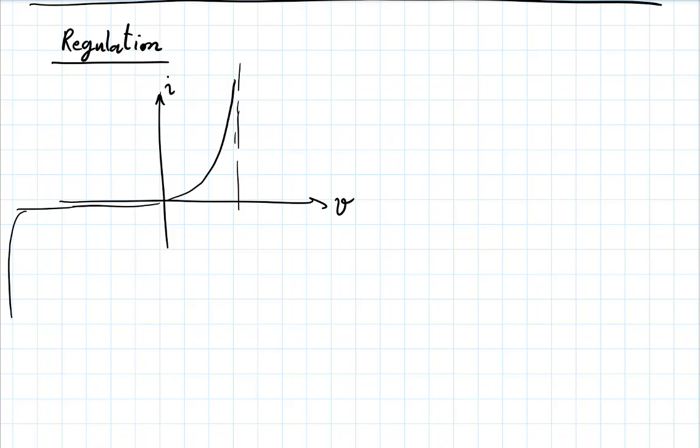Not for the full range of currents, but in forward, and this is exaggerated, of course, if you went to 0.7 volts, you would get an almost straight line for voltages around 0.7. Or in reverse, if you went to, let's say, minus 5 volts, depending on the type of diode, you would get an almost straight vertical IV curve.